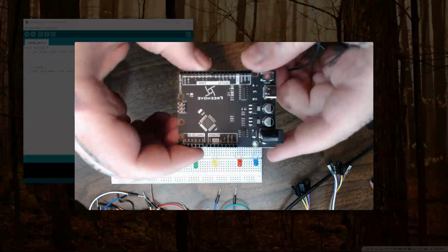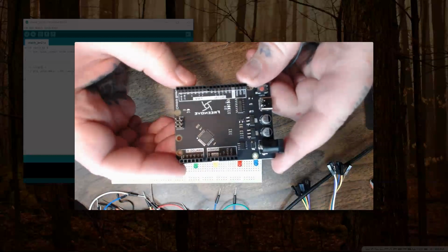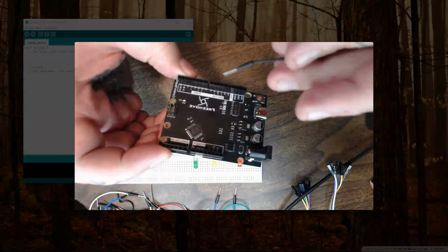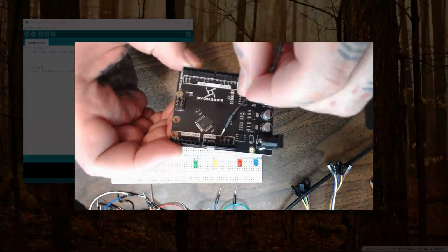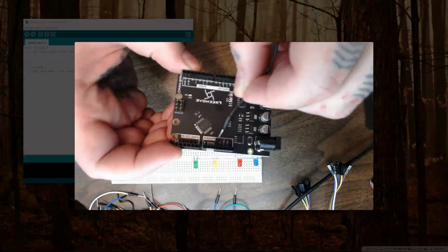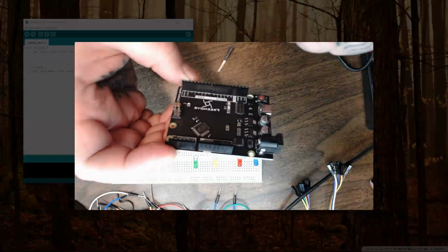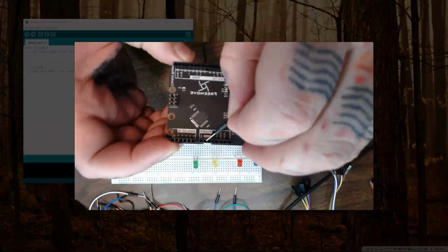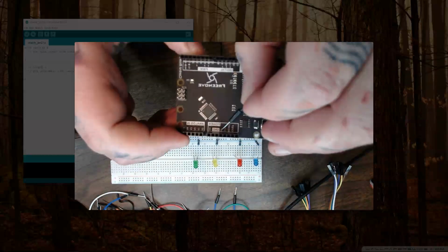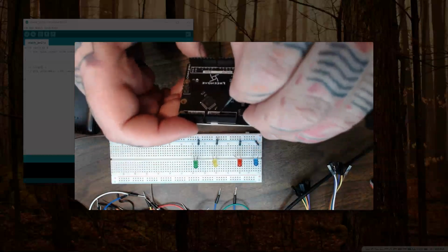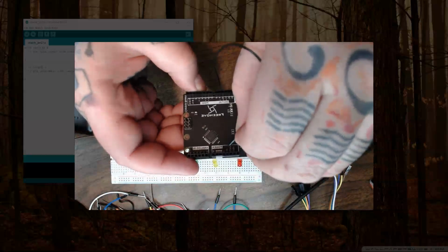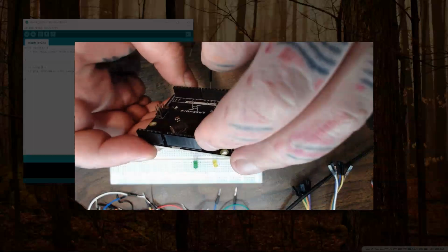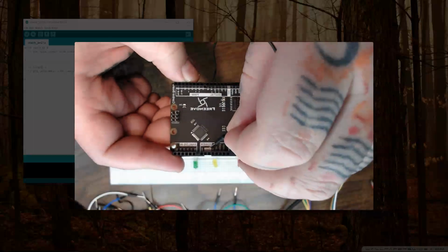And on the Arduino itself, again, you're looking for the power section or anything that says ground or GND. So you can see over here, I've got my power and I've got ground. I've also got ground over here on this side, but I'm just going to stick with the ones over here. It's arbitrary. Now, when you're doing this, this is where it gets kind of annoying to read these, depending on where it is. You really want to make sure that you've got it lined up and not plugged into the wrong pin. Because sometimes it happens where you put it in, you thought with your eyes you got into 10, and you got into 11 instead.